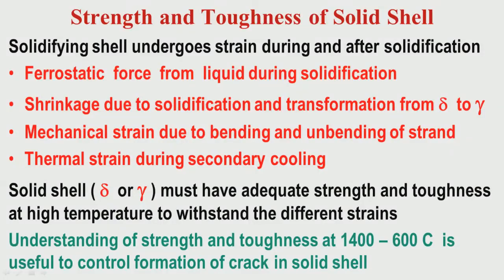That is very important. So while discussing the quality of the cast, that is why we have come to the role of chemistry, the role of segregation, because the role of segregation finally impacts the shell thickness, solid shell thickness. So that is important. Now, as I was discussing the different strains, I mentioned ferrostatic force from the liquid during